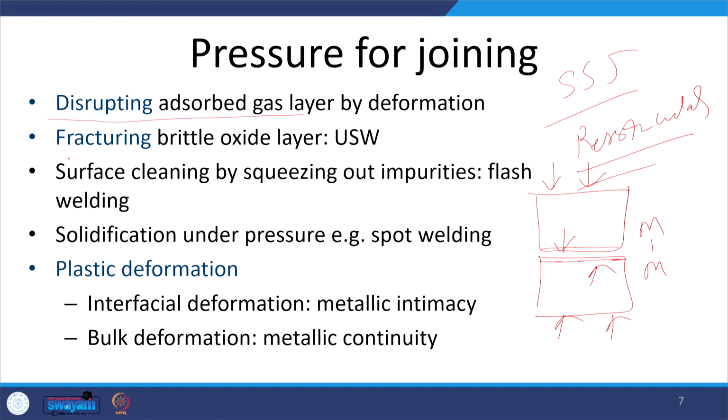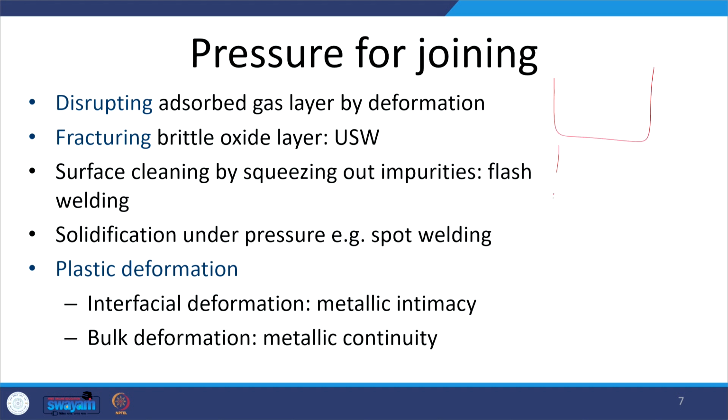Okay. Then the fracturing of the oxide layers. Say here we have the two components and the pressure is being applied. So, controlled plastic deformation at the surface layers will be taking place. At the surface we have the oxide layers, which are hard and brittle. Okay.